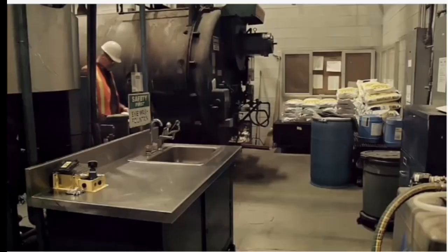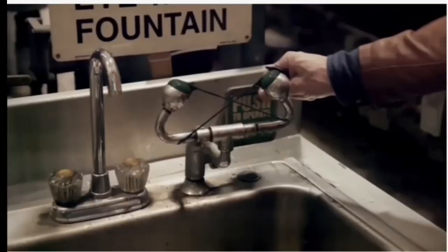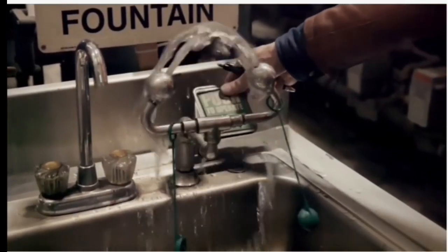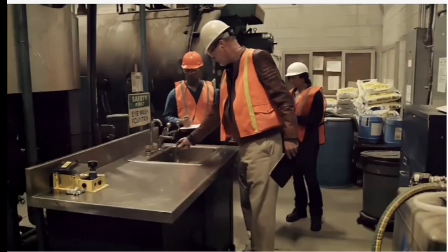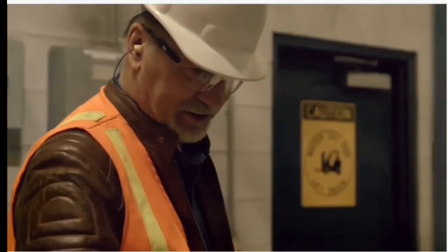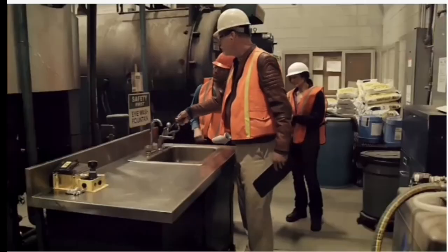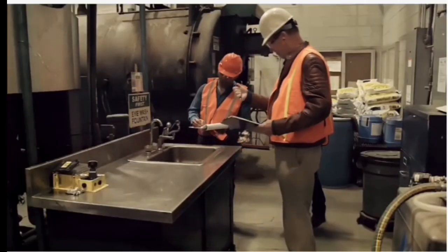Certain industries are required by Oregon OSHA to have eye wash station equipment. Here, our team is inspecting one of their eye wash stations. This is a plumbed eye wash station, so they're checking to ensure it's properly capped, the water flows clear, and it's running hands-free. If you have a portable eye wash station, you'll want to check a few different things, like verifying the fluid is changed on schedule.